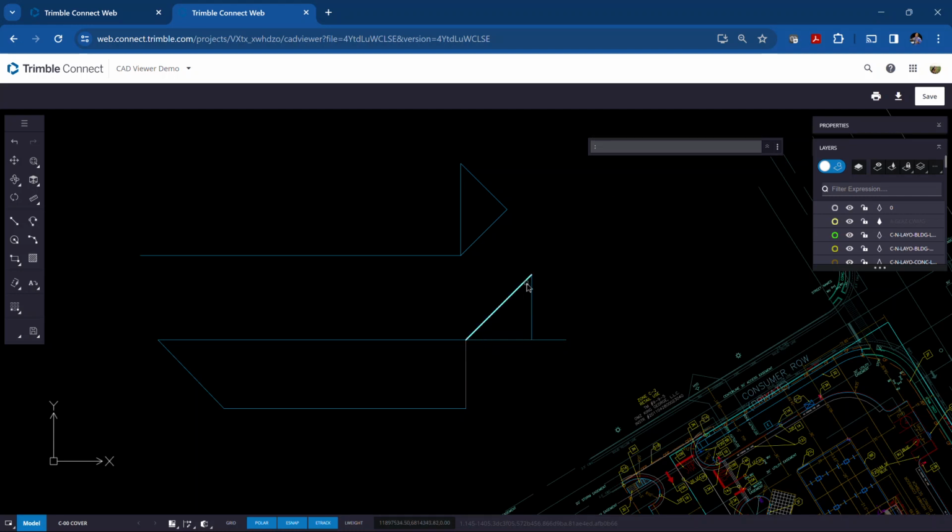It went over 50 and up 50. So that's how you draw in a line that would be precise, right? And again, the line command, you can start either from the command line or from the toolbar over here.